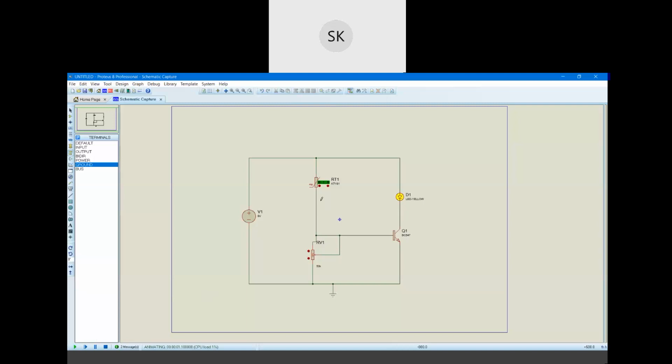You can see that for 25 volt itself, the LED is glowing. That means that our fire alarm circuit is totally going to be failed. It will just ring all the time. It will never stop. Okay, so we need to adjust its resistance accordingly, right?